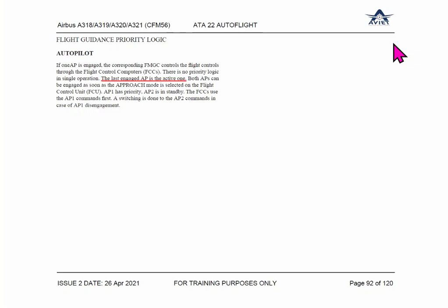So the backup nav, which system does it use to function? Your flight plan will be available on MCDU because MCDU is continuously getting the flight plan from the FMGC. Considering that it can fail anytime, that's why the backup nav will be active when FMGC input is not coming. So it is available in both MCDUs. The only thing is MCDU will not interact with FMGC now because both failed. If either of the FMGC is working, it is okay.